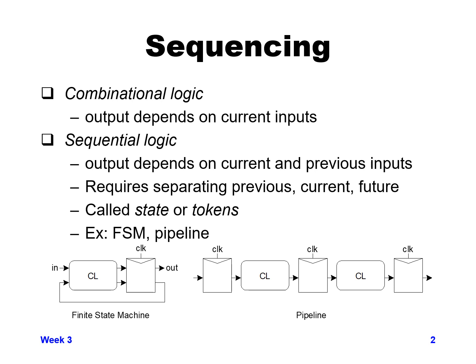And the output of that sequential will change, go through some combinational logic, and it might take some time to get through that combinational logic, but eventually it should provide a stable value as long as all the inputs to the combinational logic change only once.